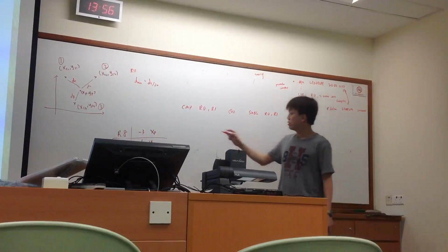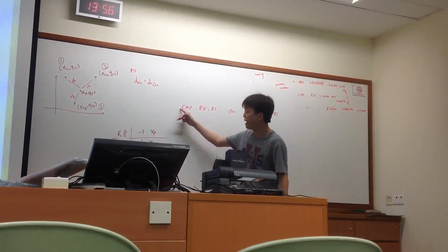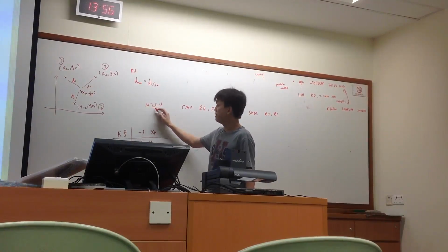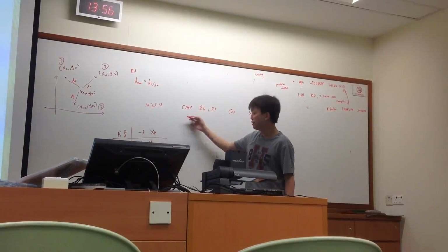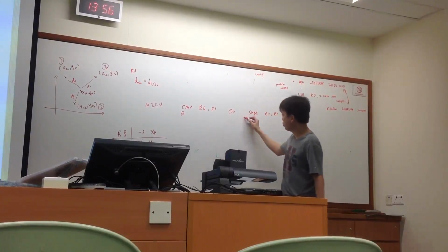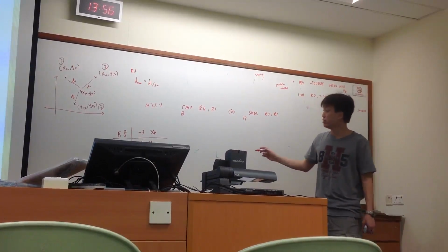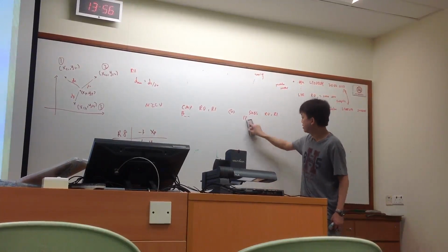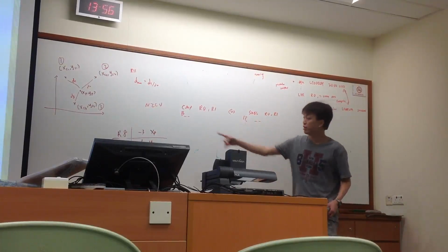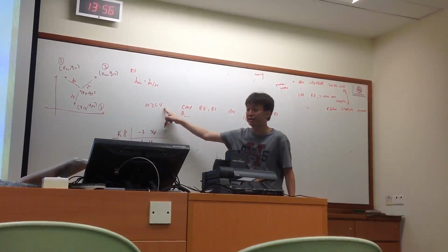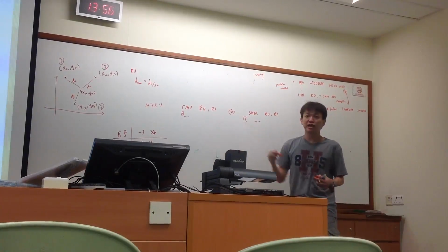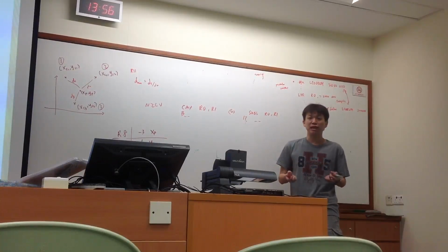Then go to this BMI. After compare, this line is trying to update your NZCV flag: negative, zero, carry and overflow. Then maybe later you can branch, you can do the IT whatever, and add in the condition you want, because this line will update your NZCV. So the next line, you can branch or IT statement, you can check the NZCV flag to decide whether you branch it or your IT statement is true or false.